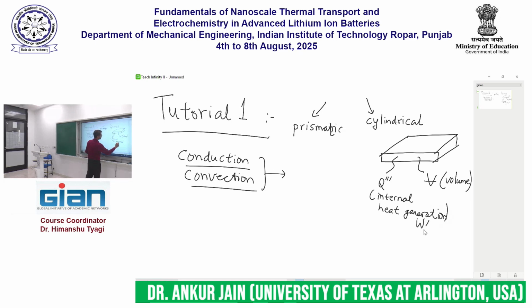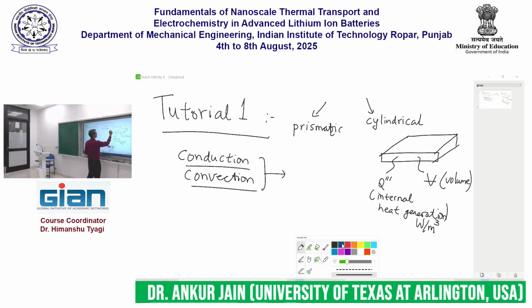This has units of watt per meter cube. Okay, so if you multiply these 2, you will get the total wattage of the cell. And my goal is to be able to remove this total wattage from the cell so that it does not start heating up. Okay, the most common way to do that would be to blow air over it.